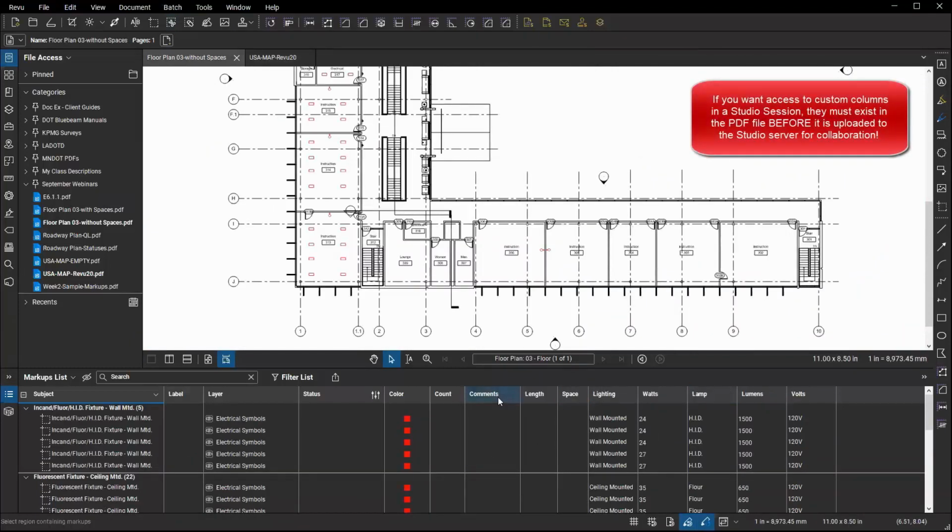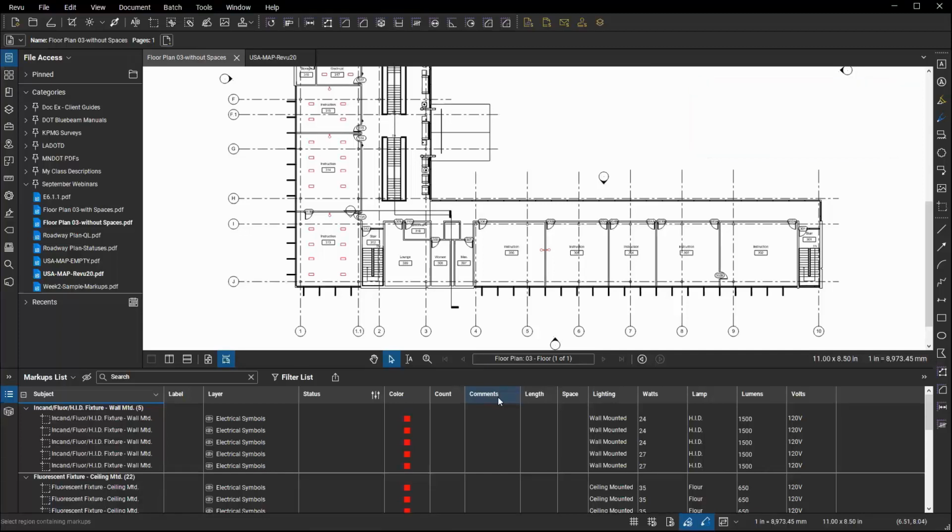And what that is telling you is that custom columns are associated with the drawing in which you create them, unless you make it part of the profile, the overall look and feel and behavior of Bluebeam that we talked about last week. And even then, if you set up a series of custom columns and you save that to your profile, it doesn't impact documents that have already been created. It only impacts new documents from that point forward. So you really need to understand, if you're going to use custom columns, how they behave and what part is controlled through the profile, and what part is controlled through the actual PDF file itself.